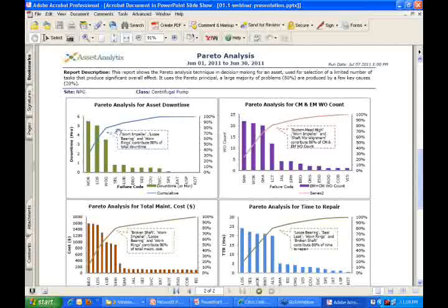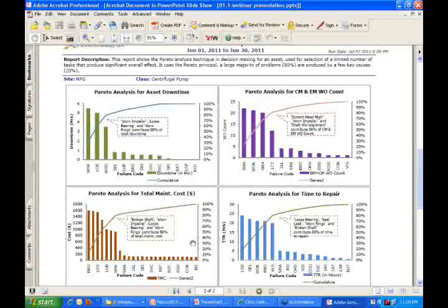So here, if you really see, we are observing that these 3 failure codes have almost 85–90% of the number of failures, or the downtime. It is causing the downtime. So similarly, you can analyze the others. The idea here is, if there is any common failure code, which in this case is impeller related problems, then maybe that is what one needs to focus on solving to begin with. Once you solve that, hopefully it will have almost 40 to 50% impact on these other factors.